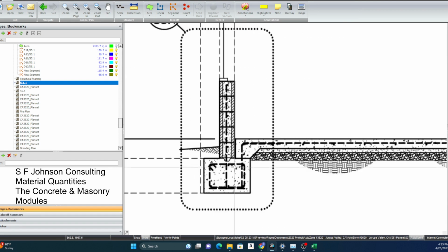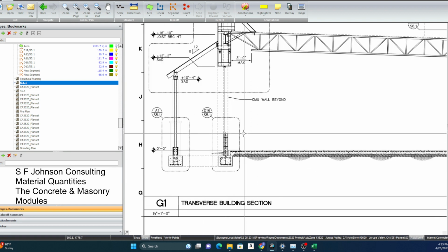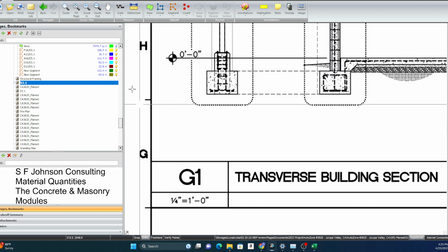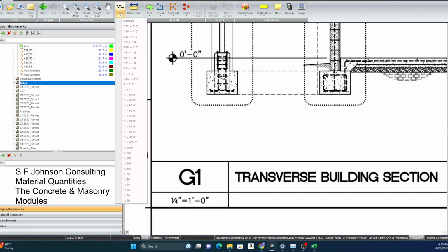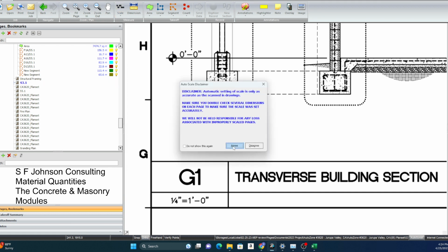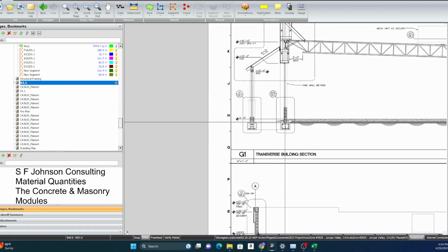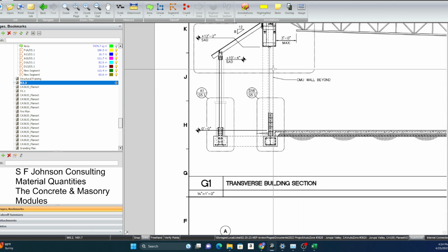I mean, you can do concrete block wall. I mean, if this is the scale, yeah, it is. Then you can measure a height of your concrete block wall and the length of it. So you have your square footage of your concrete block. It looks like it is like 3-4 feet. It's typical 3.5 feet. Let's see. Because you have your stem wall, right? And that's where we build our structural stuff on. This has a little one. That's a bigger one. That's a window, most likely. Or CMU behind. Okay.